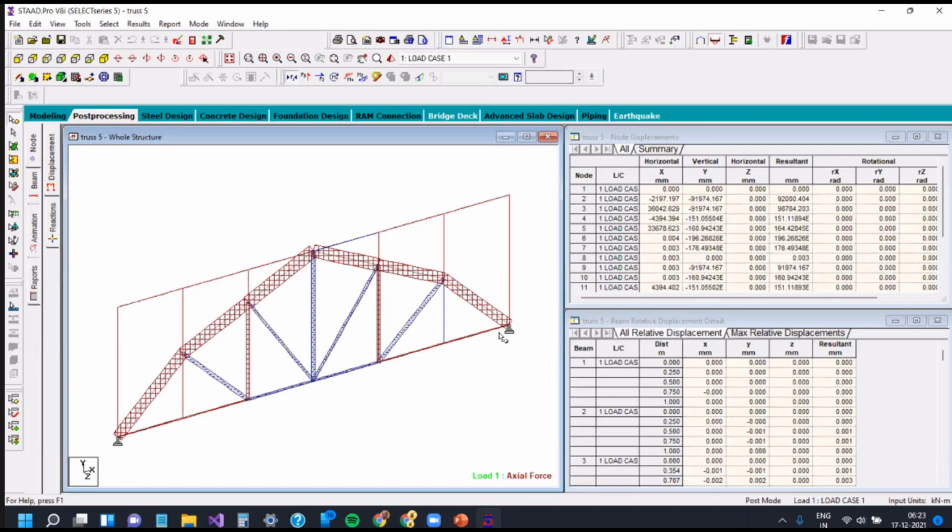See, these kind of spandrel arch trusses are very common. Now you can see this gives you a beautiful idea about how the tension and compressions are varying. You can see here the variation of compression is like our Warren truss. But if you take a Warren truss, the web members will change between compression and tension. So what we are seeing is a Warren truss action combined with an arch action that happens in a spandrel arch truss beam in the girder.